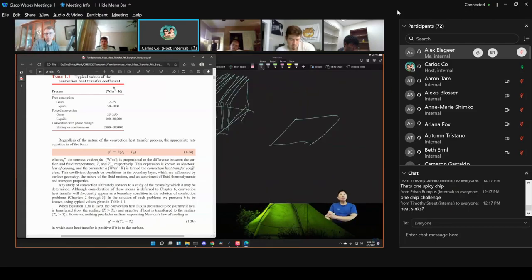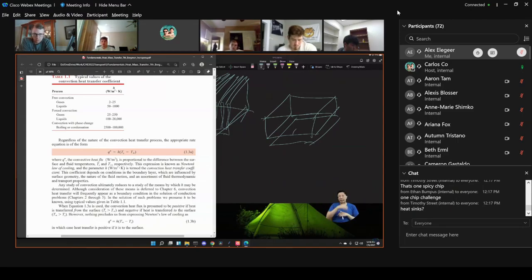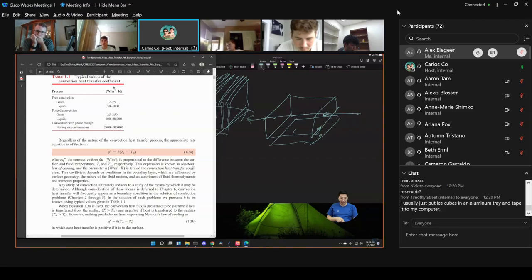The alternative is to get what is kind of like a box, something like this, and that's typically made of metal. So the bottom surface is made of metal, so there's good contact, thin good metal, and you've got liquid that flows in and liquid that flows out, right? The metal to metal contact between the liquid cooler and the chip is very thin with very good metal conduction. And so there's minimal temperature difference between the surface of the chip and the lower surface of that liquid cooler, should you call it that.